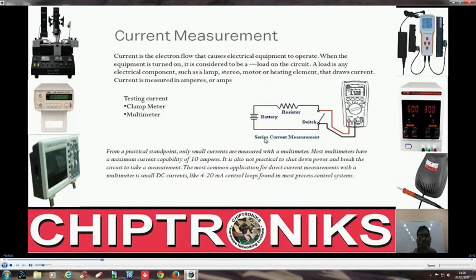So never try to measure current with a normal digital multimeter, because the way I'm saying this is a logic. The logic is that all electronic PCB circuits are made keeping voltages fixed at a specified location, right? Current varies according to the type of work you are doing. If you are running a highly intensive graphic application on a notebook motherboard, in that case there will be a requirement of higher current.